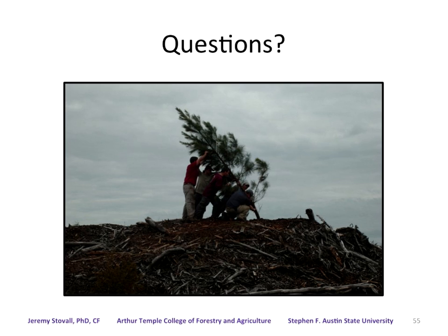So Niels has another question. How deep should we go for soil test samples? I would say it probably depends on the site, but really you want to test soil where the rooting is occurring. And so, you can dig a deeper hole, a few feet from a tree. And if you're hitting almost all the fine roots, which typically occurs in the first 6 or 8 inches, sample the first 6 to 8 inches.